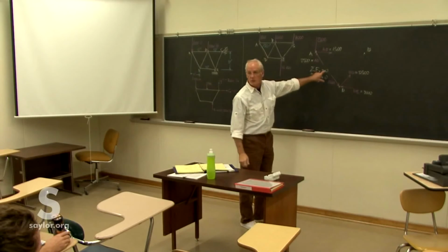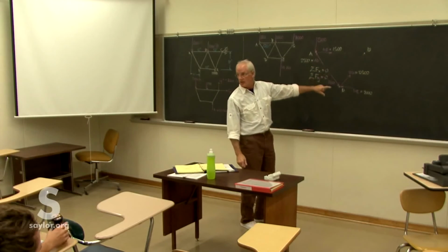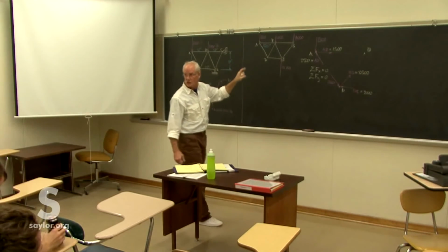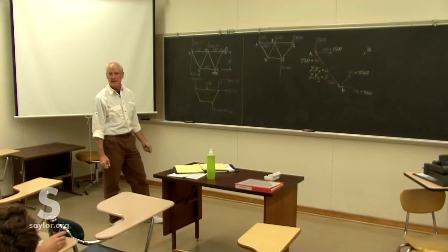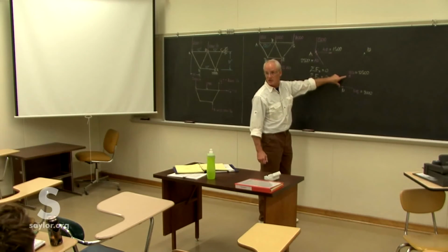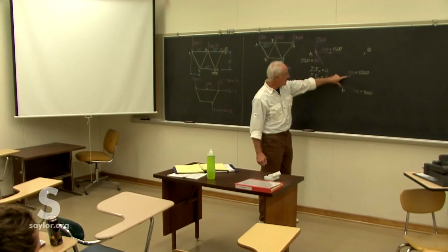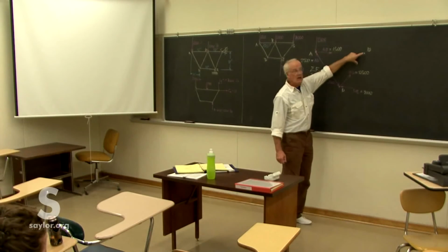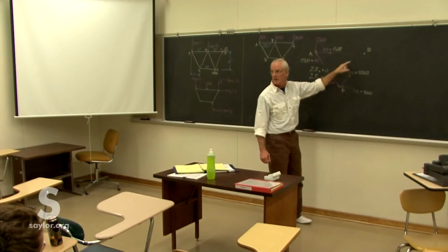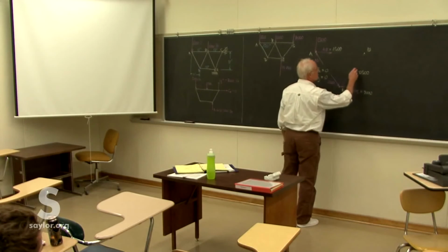and again, my recommendation is draw the joints as you solve them about where they lay, at least in the same spatial organization. You're just less likely to make a mistake. It's much easier to transfer the force that you found down here on joint D up to joint B where it next acts if you draw it this way. Much less likely to make a mistake.